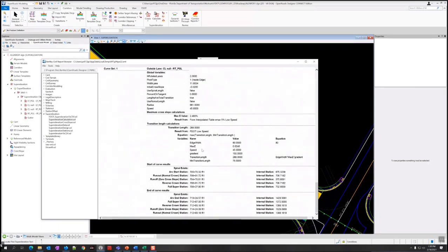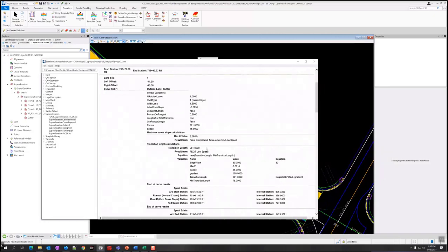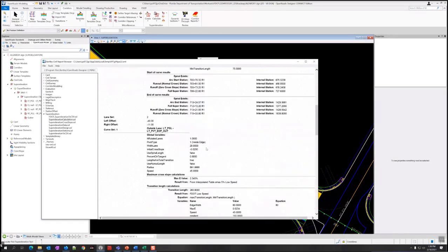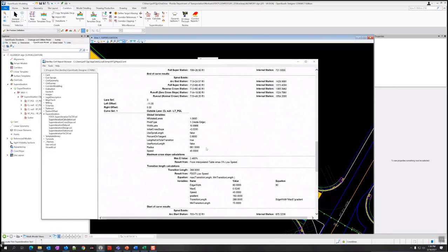So that's just a quirk of ORD. When you calculate super elevation, I think when you recalculate, it doesn't do it correctly. It might have had it correct the first time. I feel like that's hit and miss. So that's why you pretty much are forced to do some manual edits on this. But the useful thing to know is that at the center line, it's correct. So go for the lane closest to the center line.